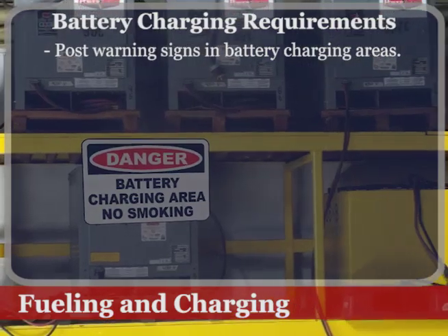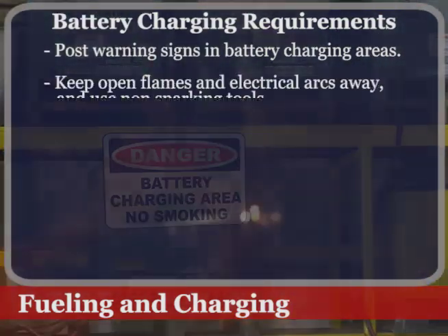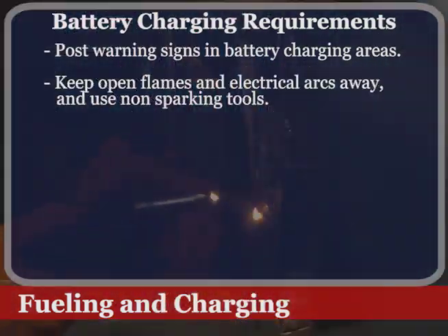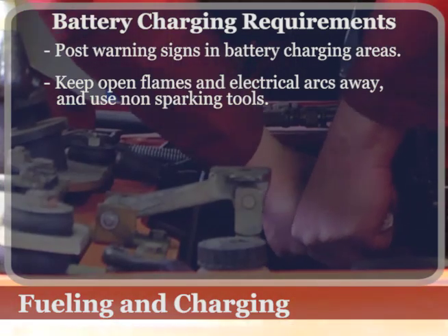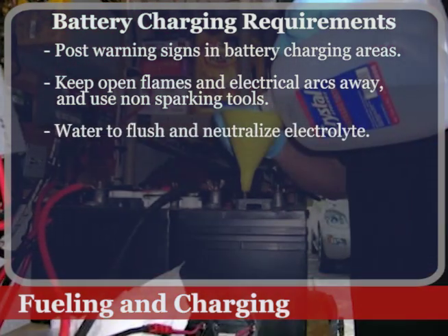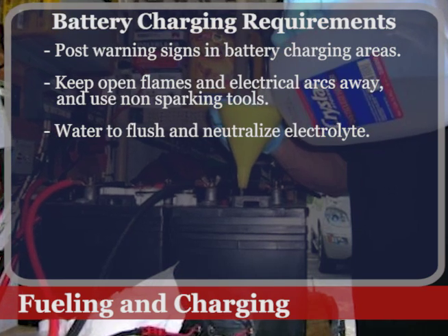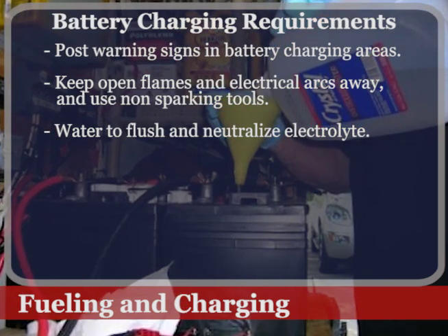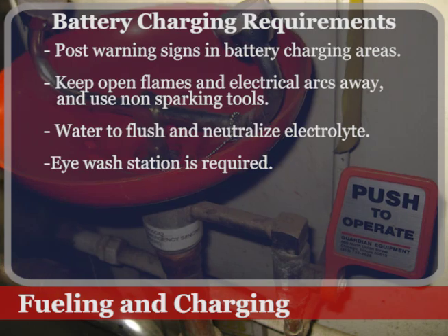Post warning signs in the battery charging area. Keep open flames and electrical arcs a safe distance away. Use non-sparking tools. Make sure there is enough water for flushing and neutralizing battery electrolyte. An eye wash station must be nearby.